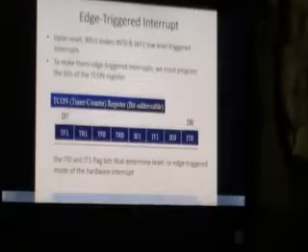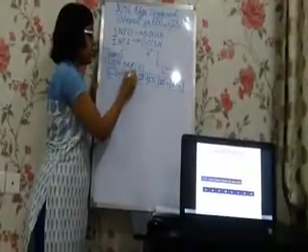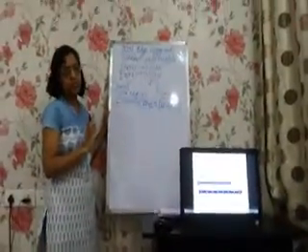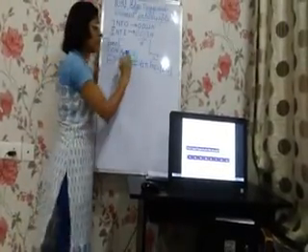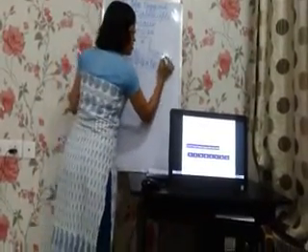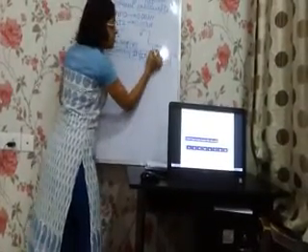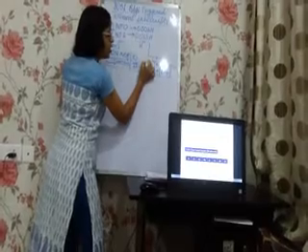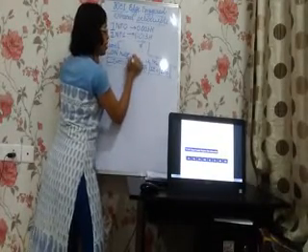Coming back to the blackboard, these upper 4 bits are used for timers, and the lower 4 bits are used for interrupt related operation. This is a bit addressable register. So this is called the TCON.0 bit, this is TCON.1, TCON.2, and this is called the TCON.3 bit.